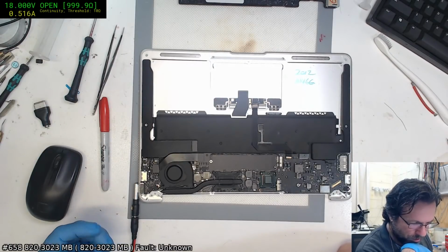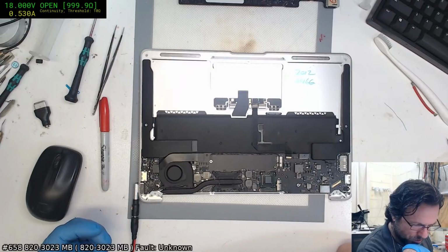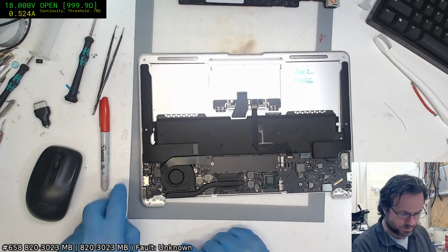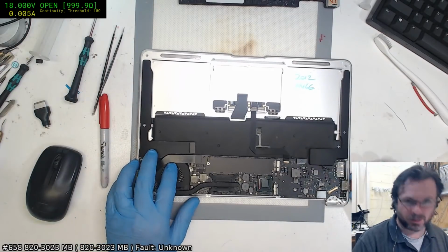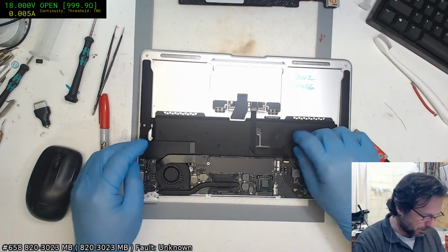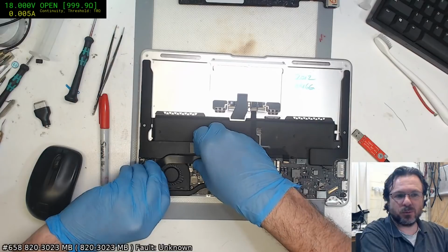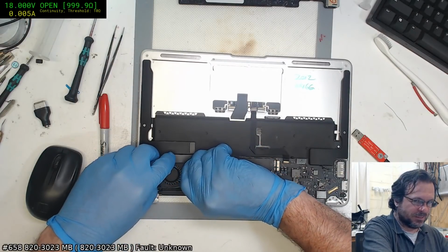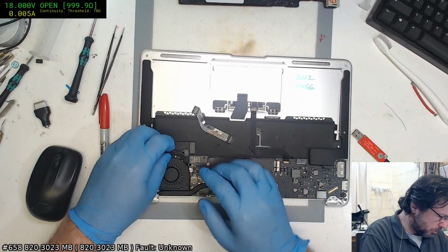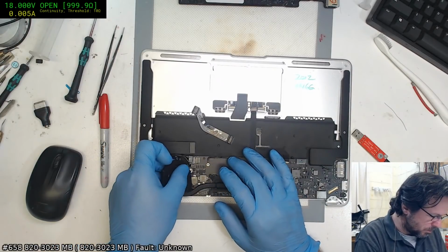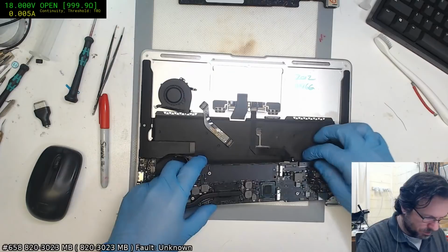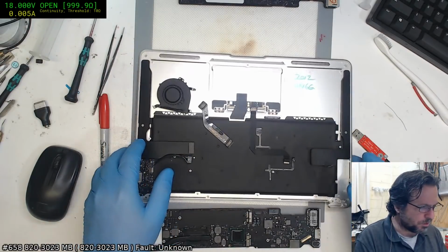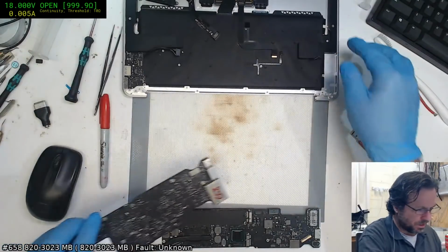That one bongs and runs. Okay, so this must have another fault, and I can see it right there. Yeah, I'm sorry. 3 beepers are just going to get straight away put into the donor board queue for me. Sonny, your solution is just going to be either change the board or reflow the RAM chips. You're not going to actually have a genuine lasting solution.